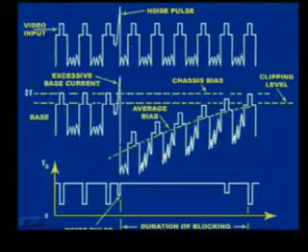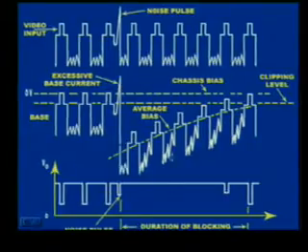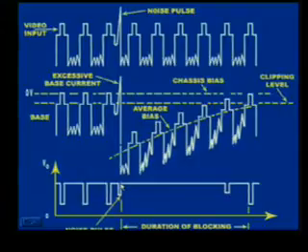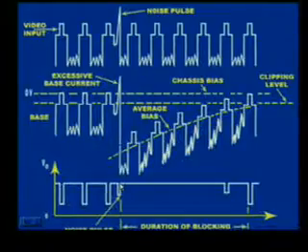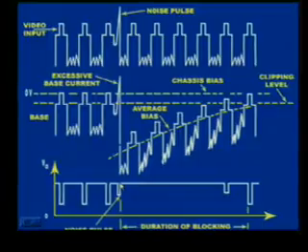As soon as this sync along with the noise enters, both the oscillators will lose their frequency stabilization, and losing the frequency stabilization means a problem in picture synchronization, and we will not get the picture or will get a picture which is unstable in form.